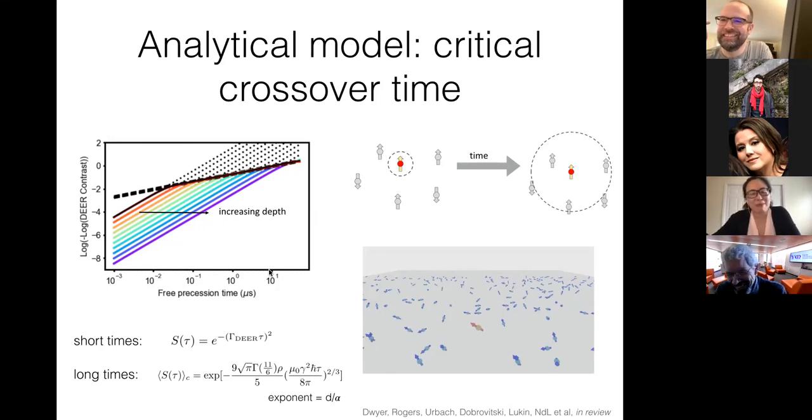But actually all of this modeling was taken out of a thesis by Jiansong Gao, who's in an MKID group at Caltech, and I think their TLS model is almost 100% from the old glass literature. The key thing is that this T1, T2 temperature dependent behavior relies on assumptions about what's limiting the T2 of the TLSs. You have to put in some microscopic model that says you have some spectral diffusion of the TLSs, and then this temperature dependence comes from the bandwidth that you're interrogating at a given temperature. Okay, yeah, thanks so much.